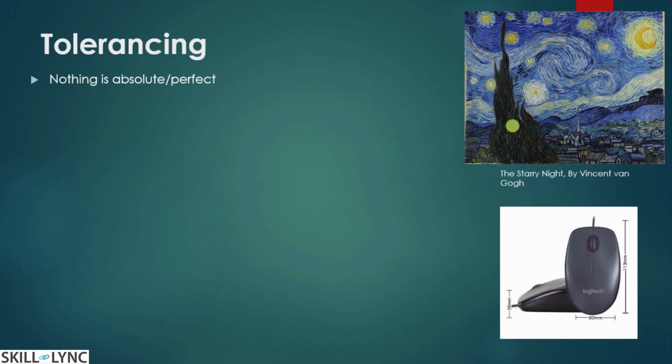In the real world, nothing is going to be absolute or perfect. There is going to be some amount of variation or difference in the component. The variations will be determined by what manufacturing capability you have, what the quality of your inspection is, and what dimension it can measure. Based on that, your tolerancing is going to get controlled. Also, you need to ensure interchangeability between the parts.